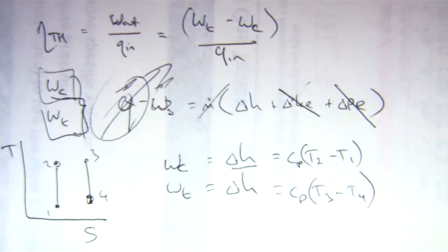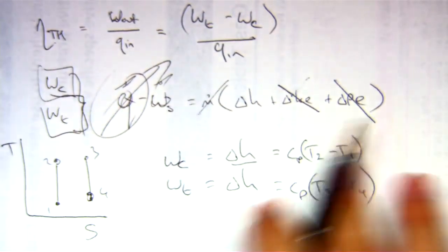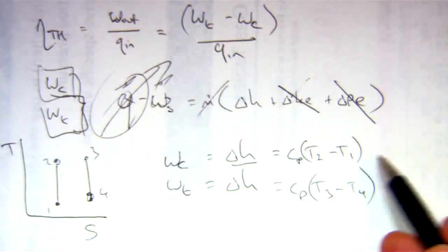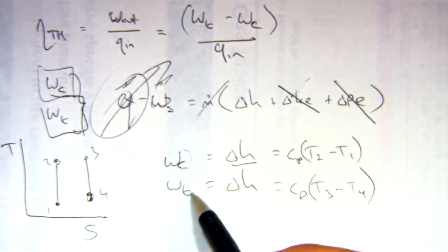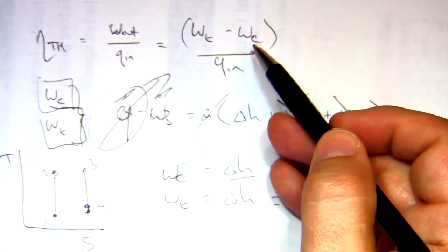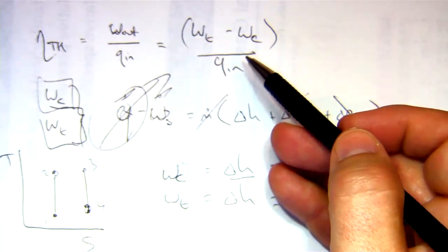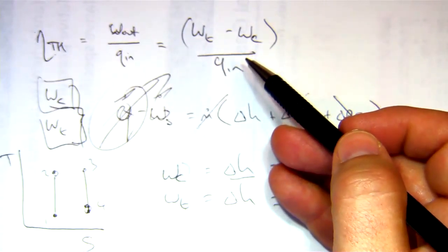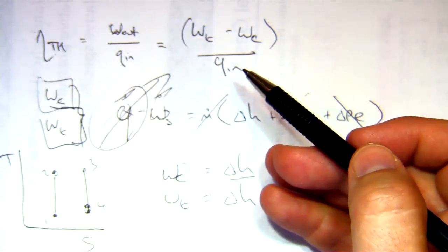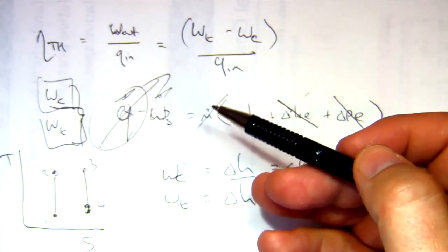Depends on how you put your minus sign. The work that comes out of the turbine will be the high temperature minus the low temperature. For the moment, as I'm writing them down, the work that goes into the compressor will be this minus this. If I write both as positives, I get a big number minus a small number, and it functions. It's shorthand by me because I'm accustomed to it, but it is worth paying attention to which way you expect the work to be going.